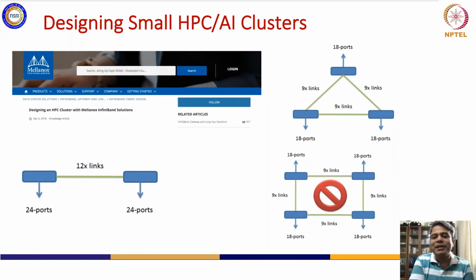One of the simplest limits is the die size. You take a large wafer, and to get a good yield, you will have a certain size of die on it. A certain size of die will be able to service only a certain number of ports, because finally you need to take electrical signals out of that die. How many ports you can take out of that die would depend on how many pins or ball grid arrays you will have from that silicon. It's a very simple way of saying that I cannot take a 2-inch by 2-inch die, because then my yield is not very high.